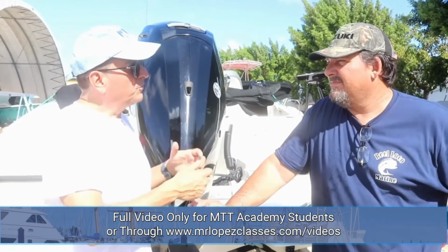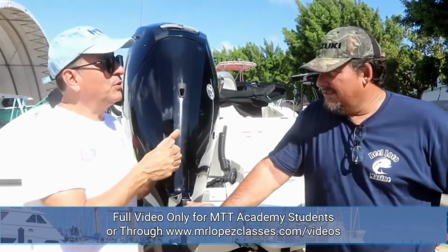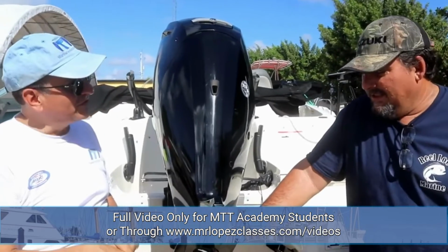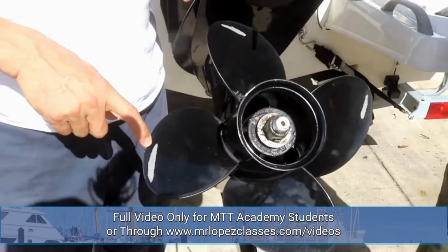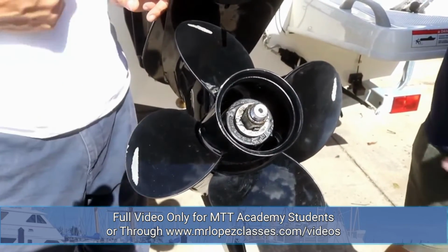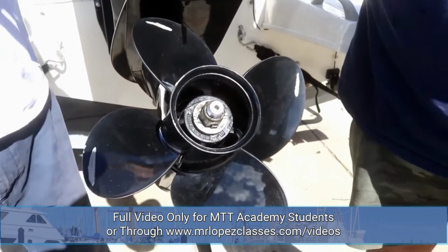Danny, every day we hear people confused about cavitation and ventilation. And today we have a great example to explain the real cavitation. Absolutely. This is real cavitation, because the bubbles are burning the prop from the pressure. Correct. The bubbles explode here and erode the metal over there. And you can see where it's eaten. Three out of the four blades are getting eaten up by the cavitation.